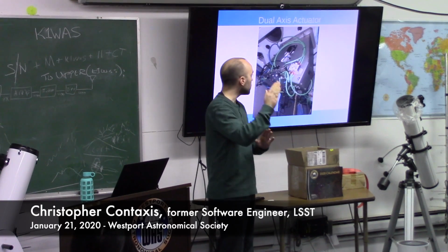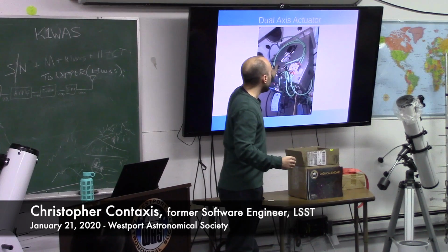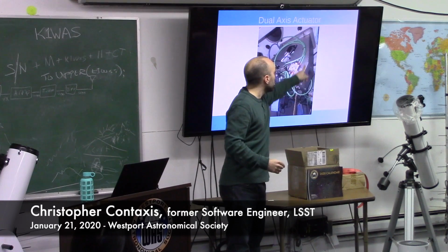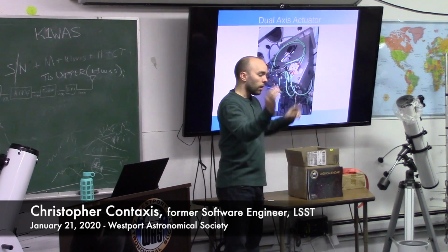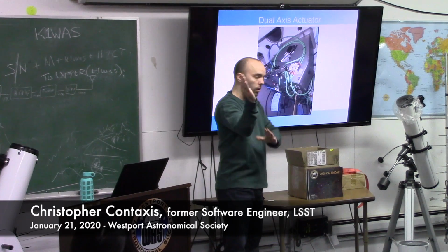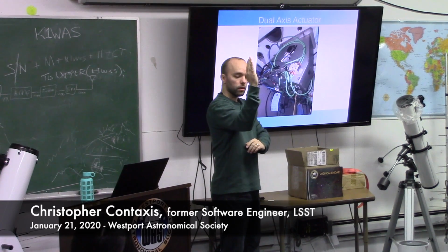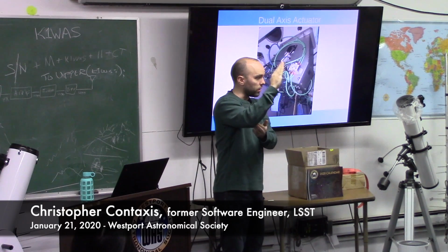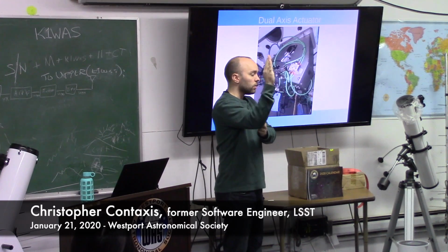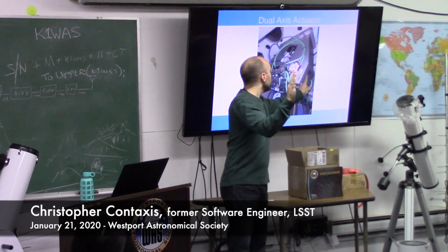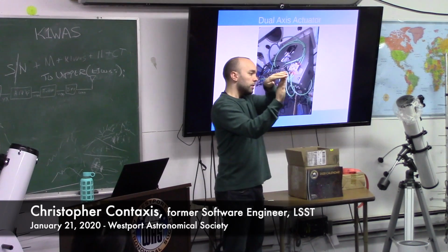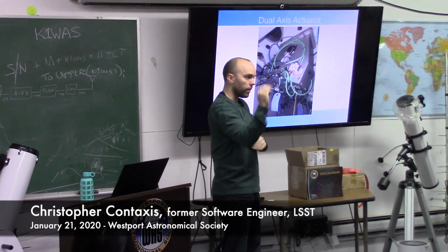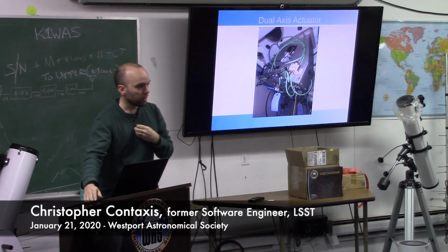So if you're at horizontal, this guy right here is responsible for counteracting gravity completely. And then the axial ones here, the ones that point directly into the mirror, are at that point responsible for counteracting the moment. When you're pointing horizontal, the top of the mirror is going to want to go this way, the bottom of the mirror is going to want to go this way. So then you use these actuators, or these cylinders here, up top, to pull this way and to push out that way so that it stays in that orientation. It doesn't turn into a Pringle.